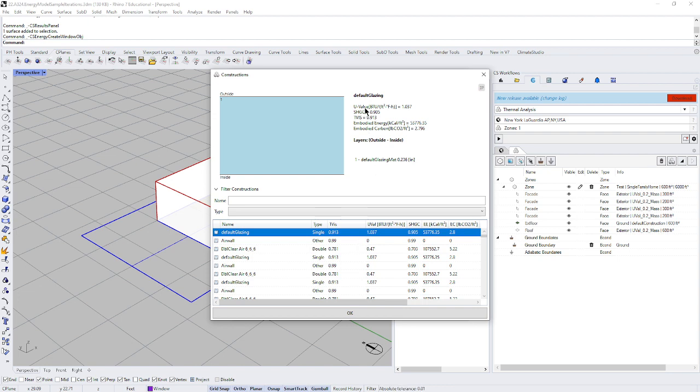We have, for example, the U value, and this is in IP units. So it's the reciprocal of the R value. In this case, it's going to be about the same. So it's going to be R1, which is really low, right? I mean, hopefully you realize that even just a little stick frame wall might have R10, even with all the thermal bridging, or R12. So the window here has a very low R value.